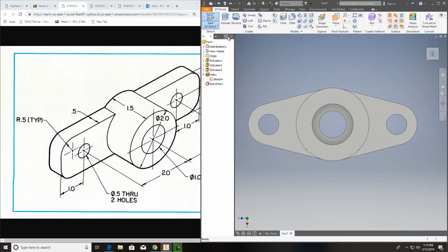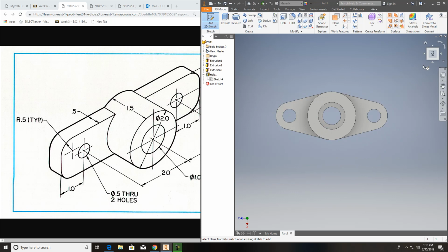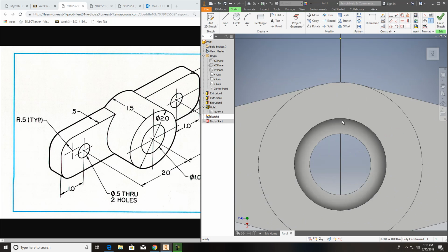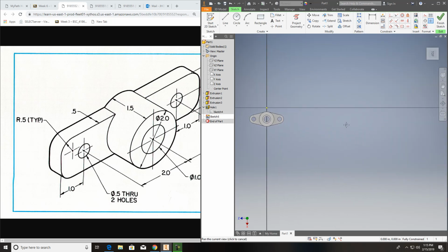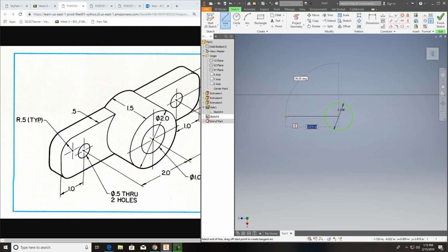Okay, start 2D sketch, and I guess we can start it on the same XY plane. We'll just put it right beside of this one. No big deal. We'll draw this one over here. It's kind of the same style. It's a 2-inch diameter, and I'll see if I can just take it. And 2-inch diameter, and it looks like this one. I'm just going to take a line from here and just straight over. Come over 2 inches. We know that one's lined up.